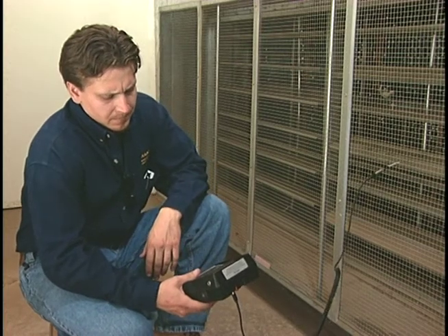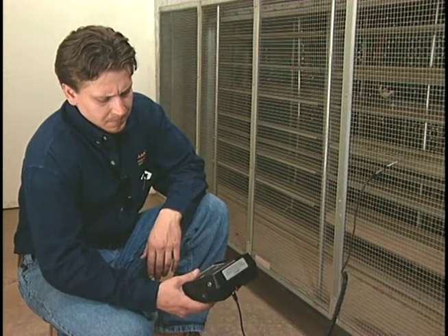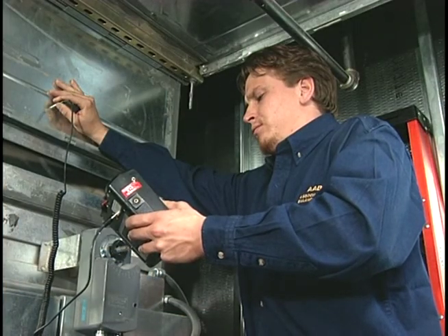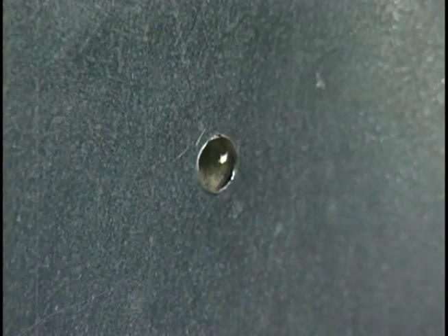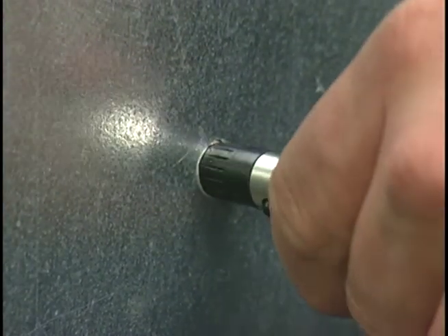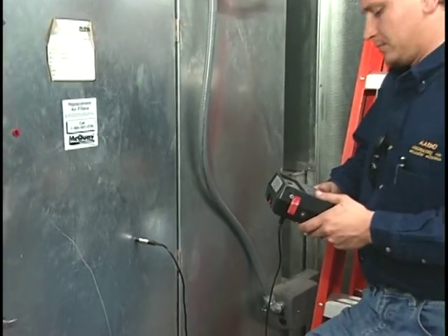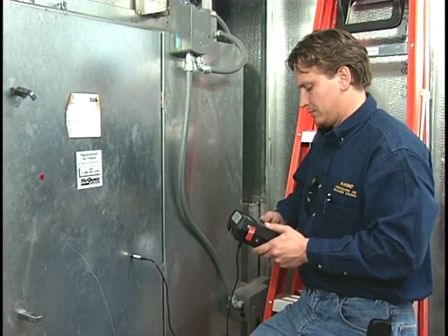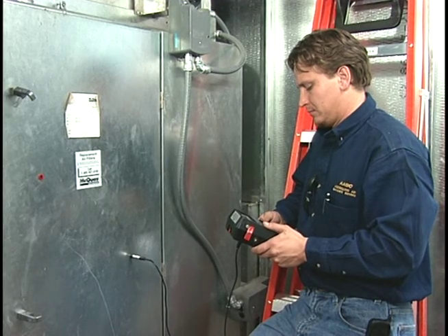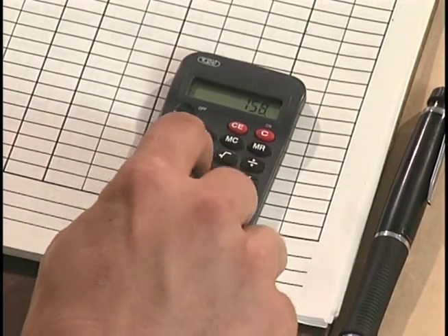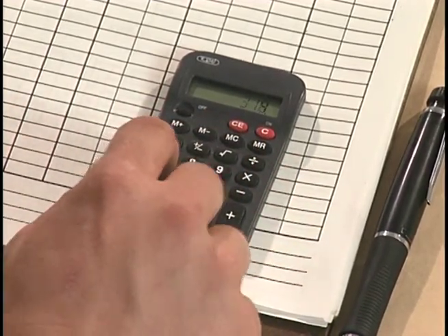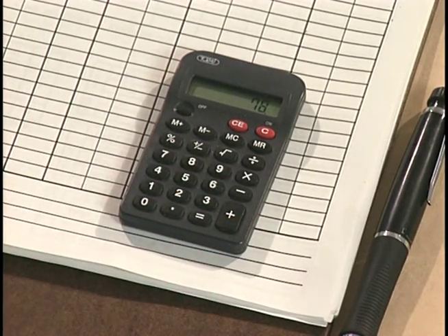With this method, the technician uses a digital thermometer to take an air temperature reading in the outside air duct and one in the return air duct close to the unit. Then the technician takes a temperature reading in the mixed air plenum. Depending on the size of the mixed air plenum and the practicality of taking readings, the technician may elect to do a traverse in the mixed air plenum by measuring air temperatures at the center of each filter. By adding the temperature readings at the filters and dividing by the number of readings, the technician determines the average mixed air temperature in the plenum.